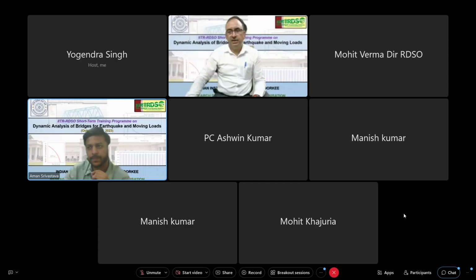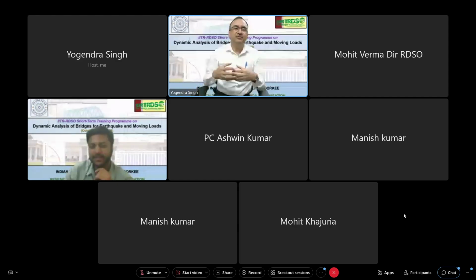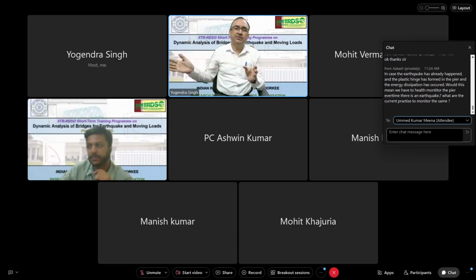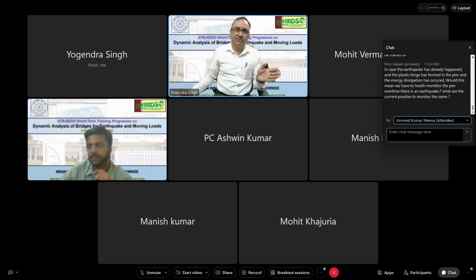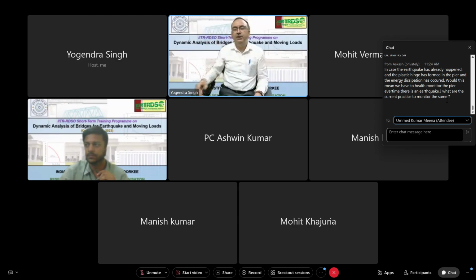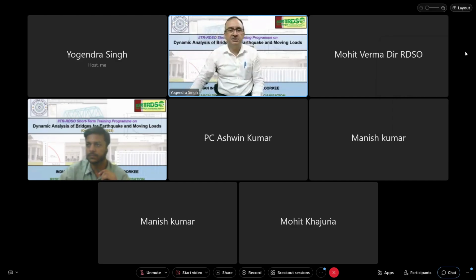Can you please elaborate further on the torsional response of bridge with unequal pier height? Well, it is an open-ended question. How much should I elaborate? Only thing is that we have to understand that it is like torsion in the building. In a building also, when one frame is flexible as compared to the other frame, or one side is flexible as compared to the other, there is torsion of the floor slab. In the same manner, in case of bridge, if a span is supported on two piers, where one pier is stiffer as compared to the other pier, the flexible pier will deform more, and due to that there will be a torsional motion about the vertical axis, and for that we need to consider the 3D model of the bridge.